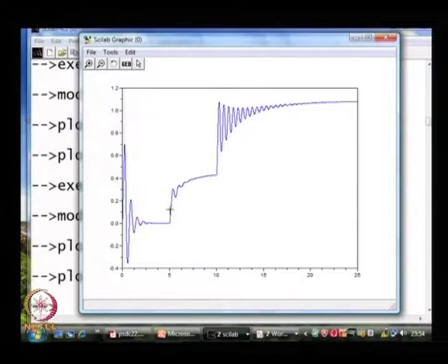So, for the first disturbance, delta goes from 0 to 0.4 roughly, this is in radians, and for the second transient also it is stable. There is a swing and there is a gradual rise as well, a kind of decaying oscillation which we see here, and also a decaying exponent. There is also this kind of rise, because of which it settles finally near about 1 radian.